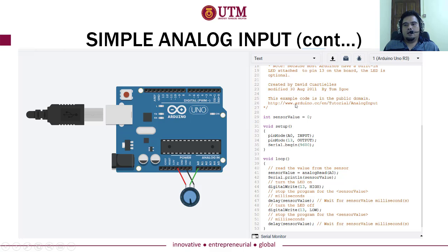Okay, so how do we show whether the analog input operation is working or not? Again, pinMode, the obvious function: you need to set your A0 as the input, because you're using A0 as the input. Of course, we also do some simulation with pin number 13, which is why we also set the pin mode for pin number 13 as output. And then